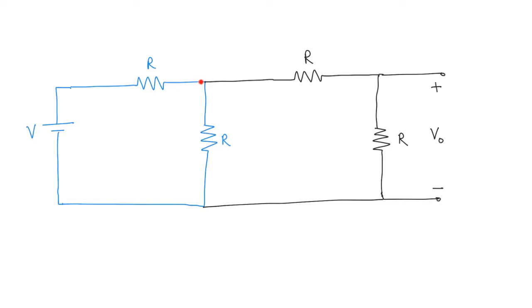The current could then either flow through this resistance, or it could flow through this resistor, right? So the current could go like this through this resistor, and then back into the power supply. Can you see that there are two paths for the current to return to the power supply? Therefore this circuit has two loops in it, and therefore this is called a multi-loop circuit.